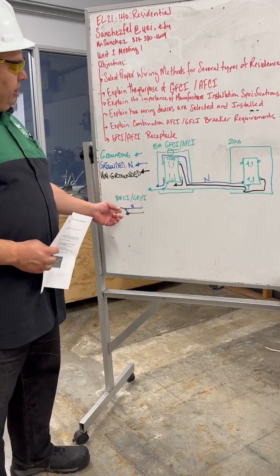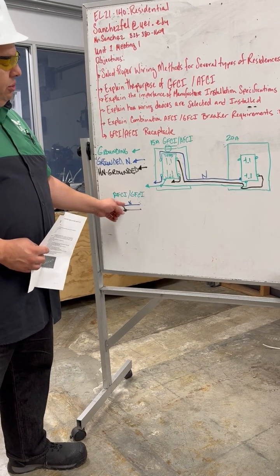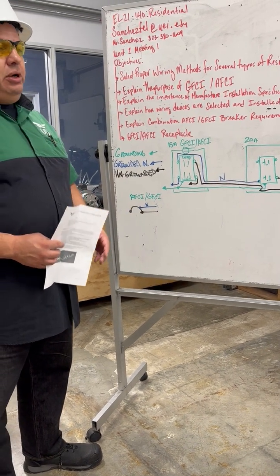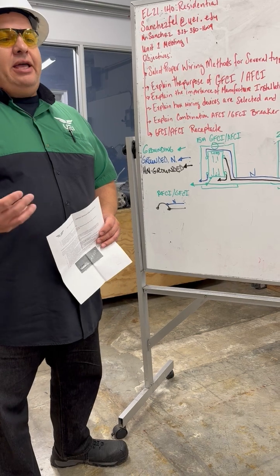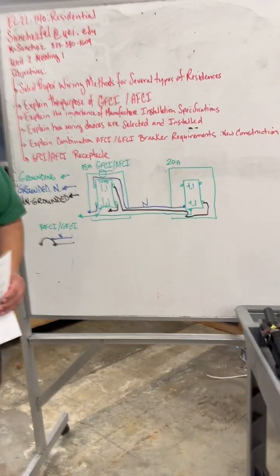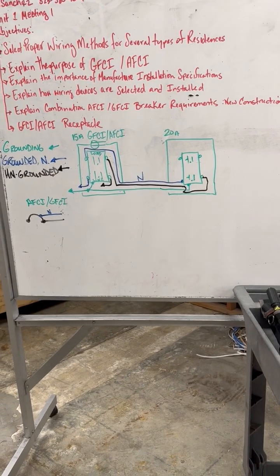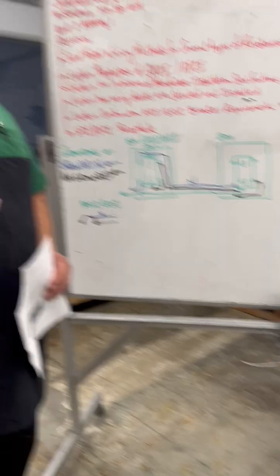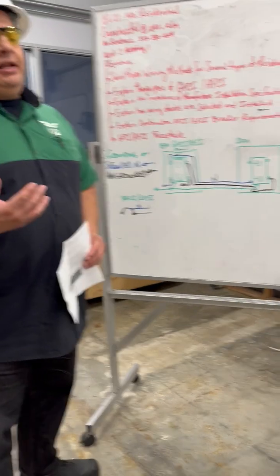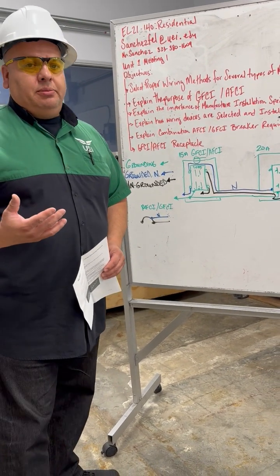But I illustrate to them the circuit breaker symbol and the fact that the neutral and the ungrounded will have specified locations at that particular breaker. In an older home, or let's say old work, those residences are not required to have had AFCI, GFCI breakers, nor are they required to upgrade to them.